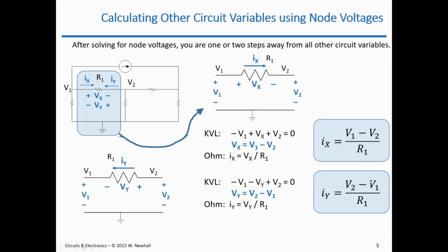You can see that down here in the equation. If you multiply this equation by -1, both sides, you get the top equation. And you get Ix equals minus Iy. Okay, so what we're going to do is use these equations for current in node voltage analysis. So let's do that.